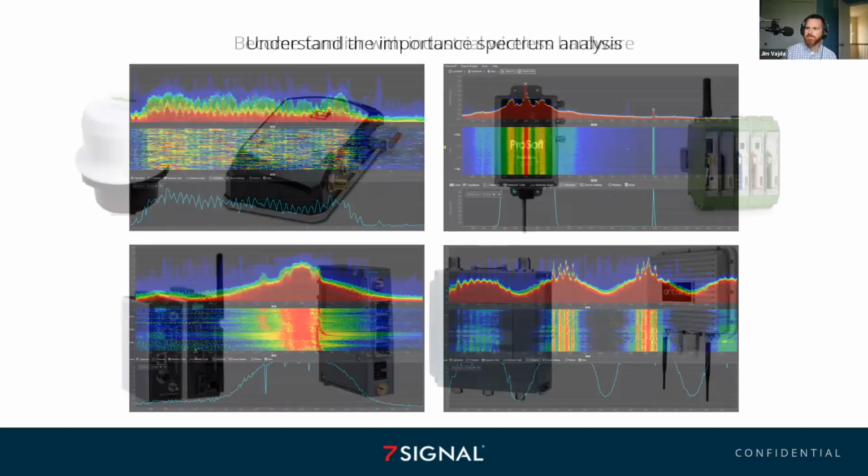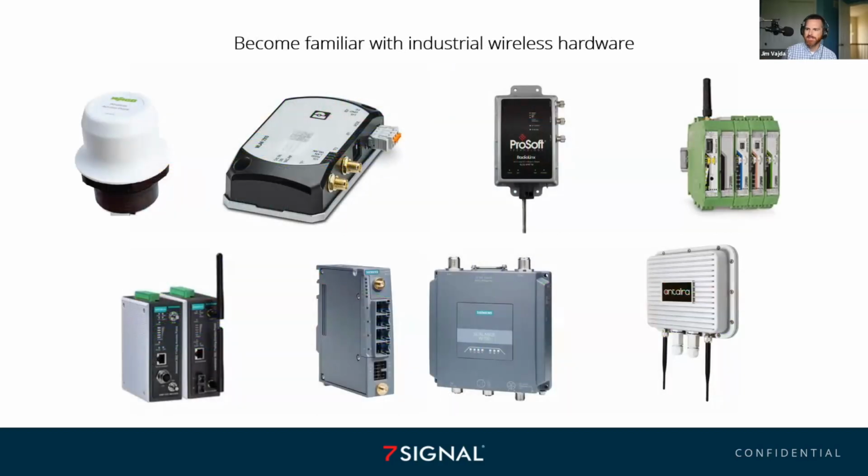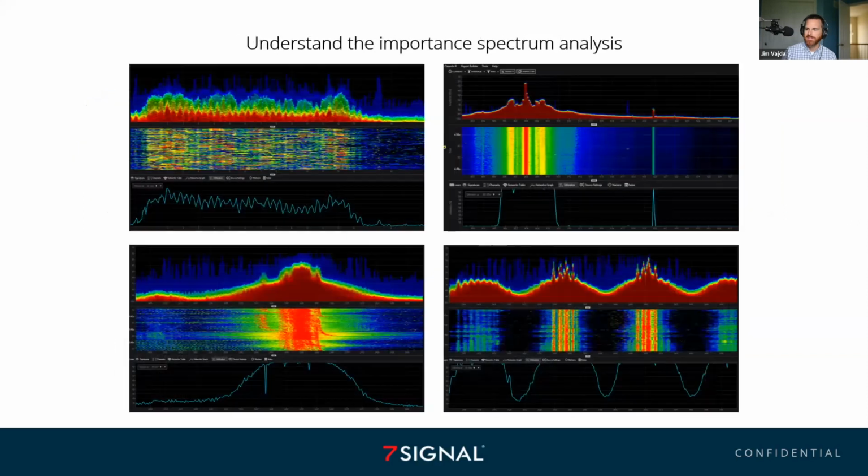What is that last graph there? Did you identify what the interference source was? Yes, that was an infrared curing machine at a roofing plant. It cured the adhesive to the backside of the roofing material. And being that that was a $500,000 machine, they weren't changing it. But at least now they know, and we were able to migrate everything over to 5 gig.